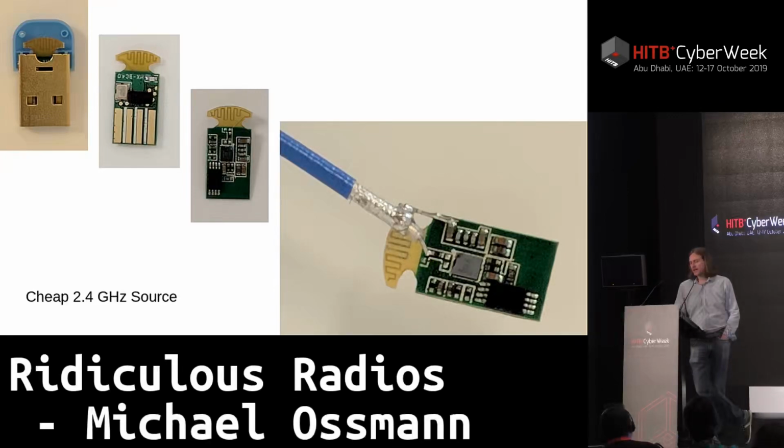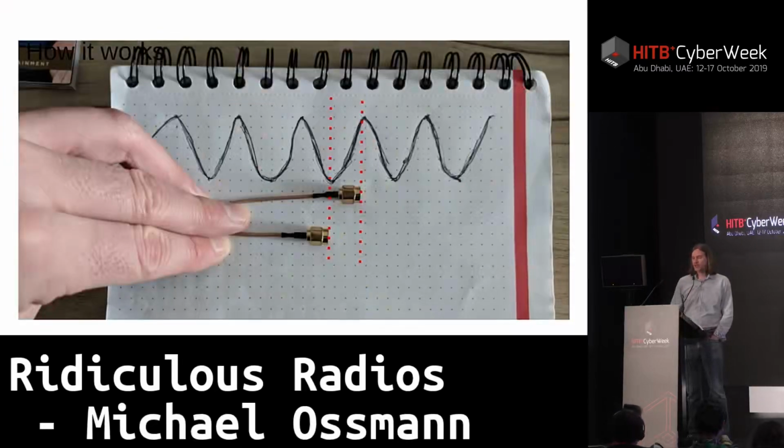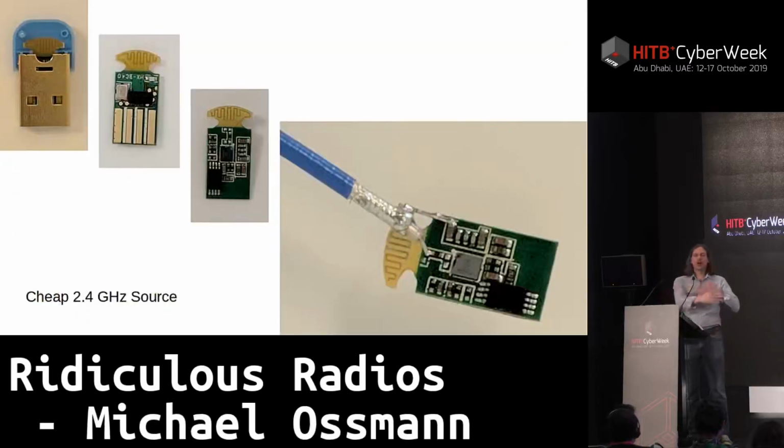We're basically repurposing a Bluetooth chip here. And so we're taking maybe a radio that we're allowed to have and then doing something we're not allowed to do with it, perhaps. And you can see we modified it a little bit. On the lower right, you can see I've disconnected the internal little wiggly antenna, and instead I've added a little cable so that I can connect it to some external antenna. And then we actually connected it into our Opera Cake, which is our antenna switch.